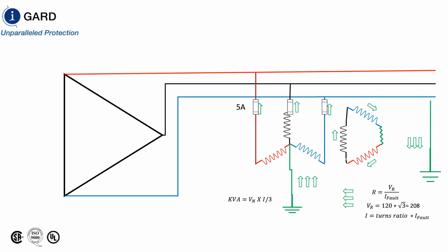So if we had a 5 kV system and you wanted to limit the fault current to 5 amps of a fault here, on a 4160 to 120 volt PT, so you can see that these ratios here, 4160 to 120, when we have a ground fault, the current goes down through the fault and back to the source, and we complete the circuit this way.